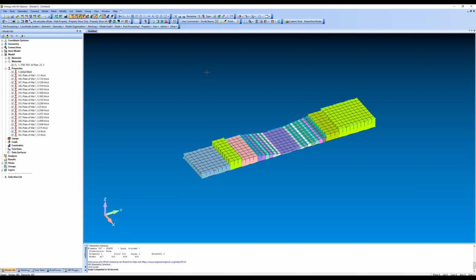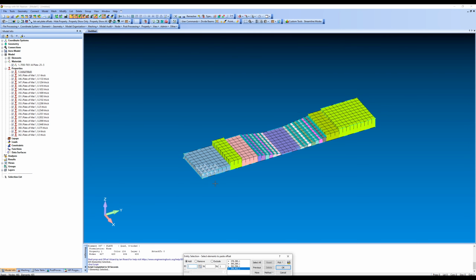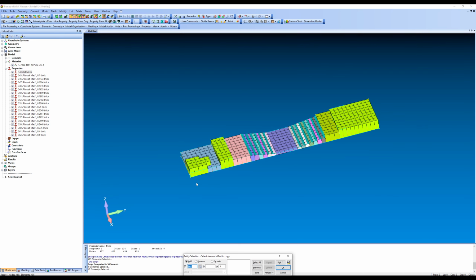What I find I do in practice is I use one of the companion tools, and it's copy, shell, offset, and prop. This is essentially a copy paste. I'll say I want to copy this element and I want to paste it here. What I do in practice is run the shell property and offset wizard for, say, a single element in this region, and then I'll copy paste them for the rest of that region. I find that to be the most efficient way. But like I said again, it depends on your workflow and the particulars of the problem you're working.